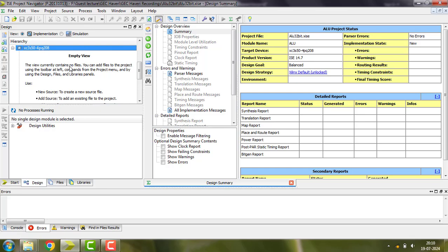But make sure you keep in mind that those 32-bit inputs will take 32-bit locations, or in other words 32-bit flip-flops. Okay, you can have something called a ChipScope. If possible, we'll try to have a tutorial for ChipScope